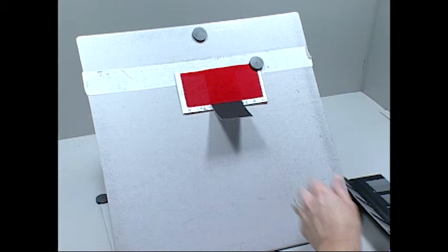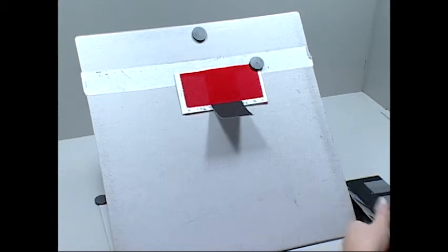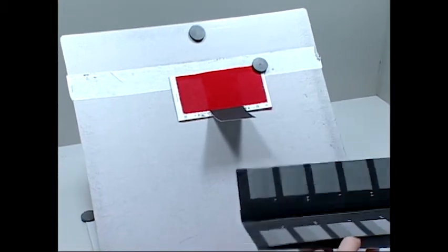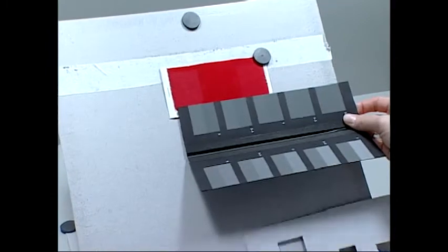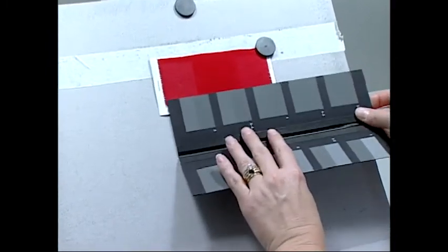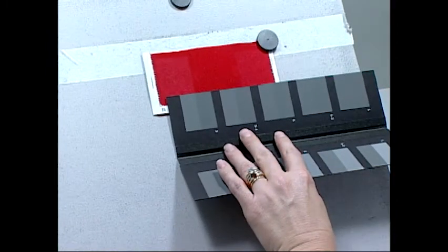The example shown here is a light fastness specimen that has been exposed for 20 and 40 hours. The left side of the specimen was exposed for 40 hours and will be rated. The grayscale is placed along the edge of the specimen with the tiles most closely matching the color change next to the exposure. Notice that the evaluation booth background is the color specified in the test method. Also, the specimen is mounted in a standardized white card so as not to interfere in the rating.